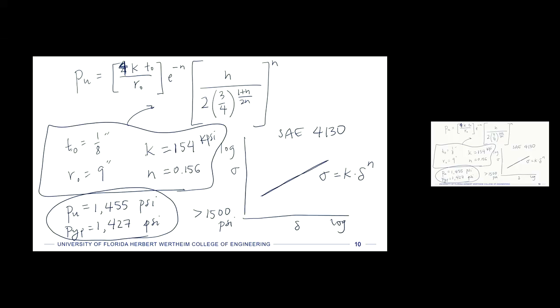And so you would be overestimating failure, right? You might think that this pressure vessel is safe and won't experience plastic collapse, but in fact it would. So don't make the mistake of putting the ultimate strength into a yield criterion, but rather use the proper plastic deformation equations.